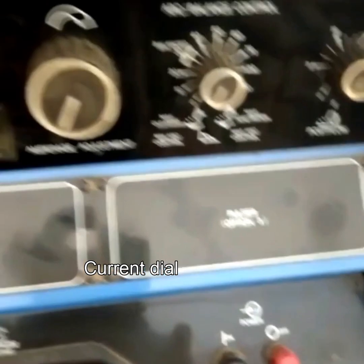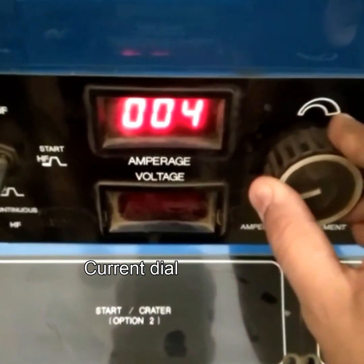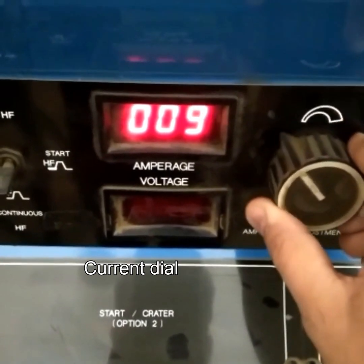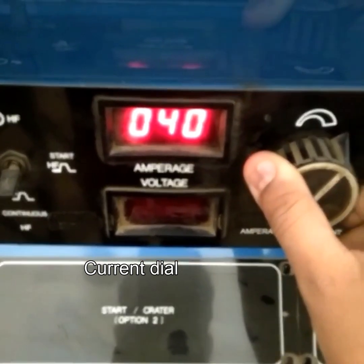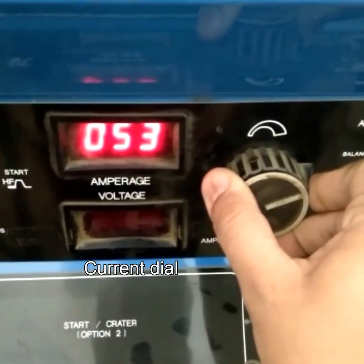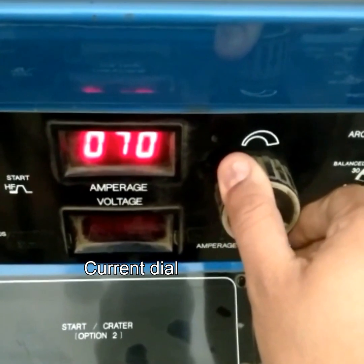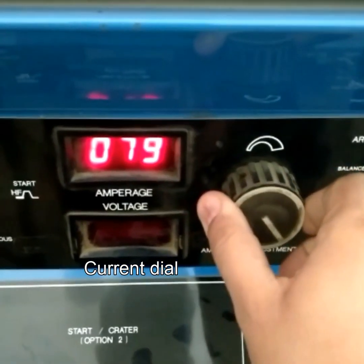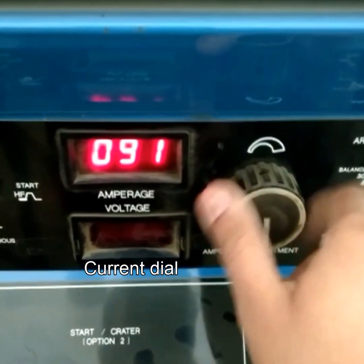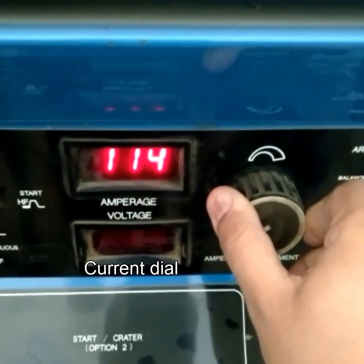In this machine, we have three knobs: the current knob, the arc balance control, and the post flow. By using the current knob, we can adjust the current up to 200 amperes. In this welding, we will weld aluminum, so the current should be 121 amperes. Current depends upon the material type and thickness. If we have a thick part, we have to increase the current.